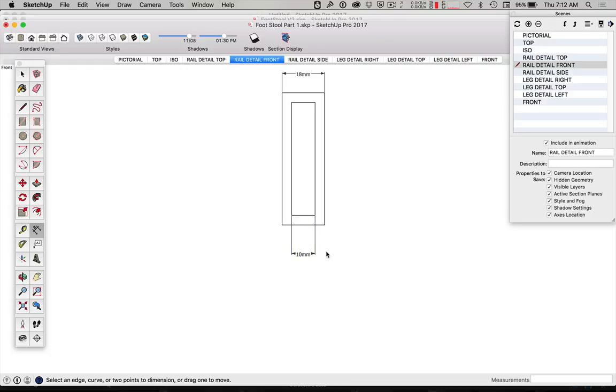So that's where SketchUp Layout is more powerful, because we can edit those quite easily. I believe I can, I won't try to double click and mess up this tutorial, but we might just put in one more dimension there on this side. We can go out there, and on the inside we could put a dimension.